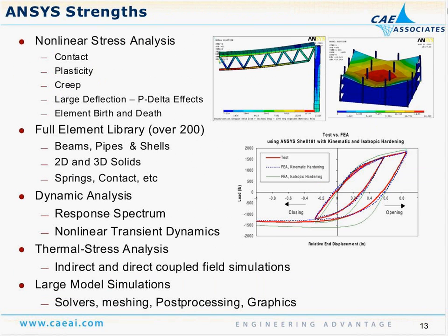ANSYS strengths. ANSYS, of course, from the structural perspective, can solve a full suite of nonlinear analysis, various contact problems, plasticity, creep, large deflection. And the nice thing about the solution capabilities is any feature of ANSYS can be integrated and combined with the CivilFEM features as well. So because they're both command-driven, they can be integrated at any point in time. Your model can be run in ANSYS, and then some post-processing done with the CivilFEM add-on features.